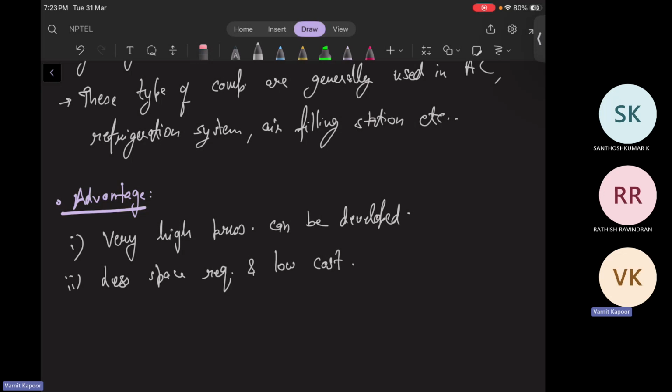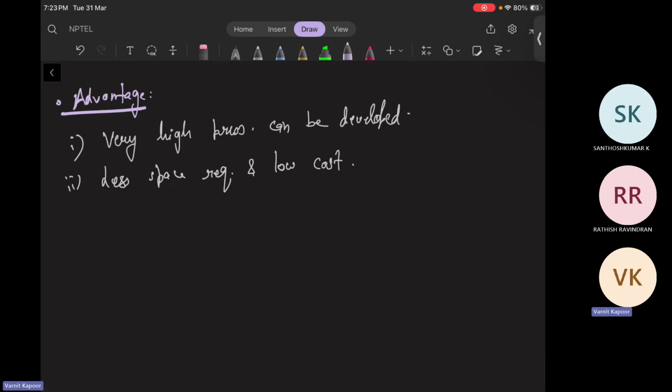What are the disadvantages? They provide intermittent supply, not continuous basically. Volume handling capacity is low. Less RPM, so can't be coupled with a turbine in power plants. They have balancing issues. Mechanical losses are there due to sliding motion during the reciprocation. Okay. Disadvantages.